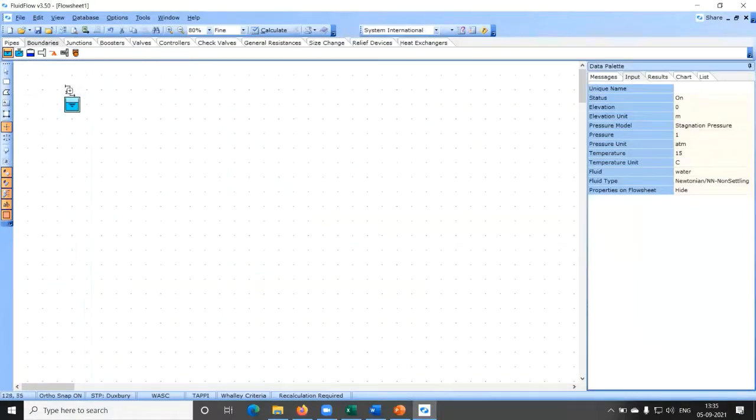So if you see, I have clicked on the flow sheet and this known or assigned pressure is still active because I needed a second one. So I use the second. Then go to the junction. In junction, I selected bend. So somewhere at the right angle here, I'll select that, right? Bend is still active. I'll go to pipe now. I'll use the first one, steel pipe.